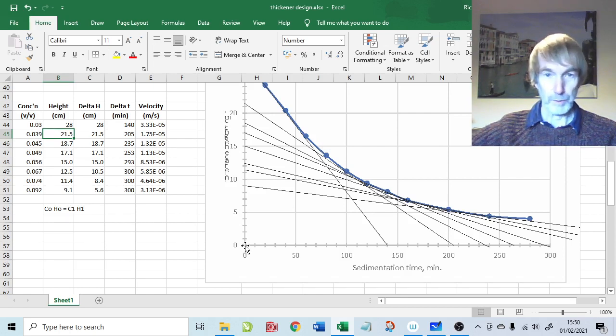The 3.9% characteristic hits the curve at this point just here, and as far as the solids are concerned, thereafter, it doesn't know whether it started at 3.9% solids settling from that height, or 3% solids settling from the 28 centimeter height. It's the same amount of solids at that particular height onwards, regardless of which scenario it started at.